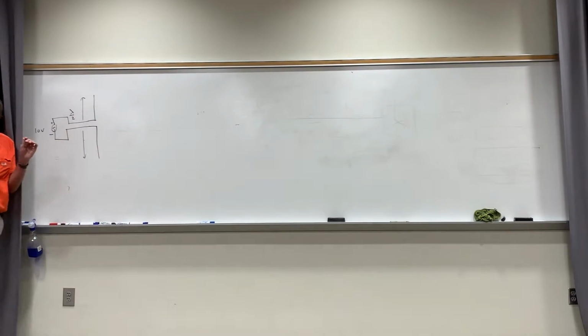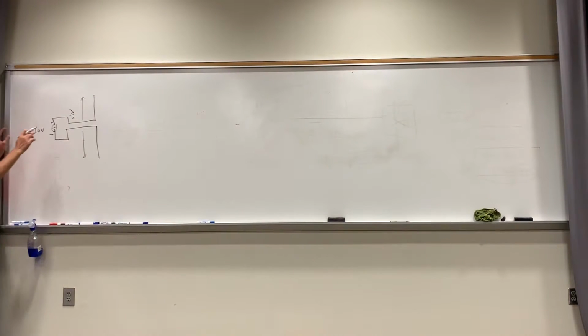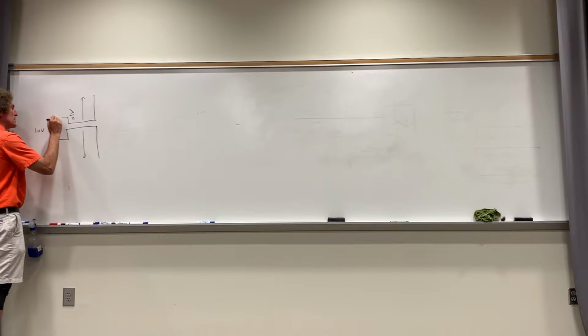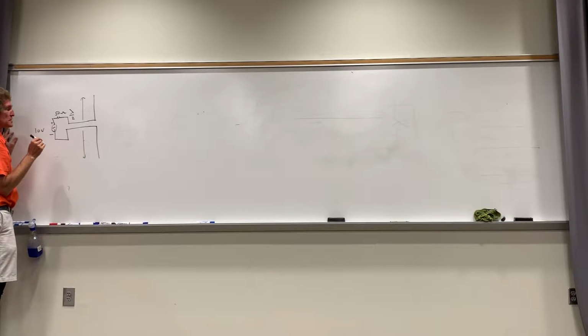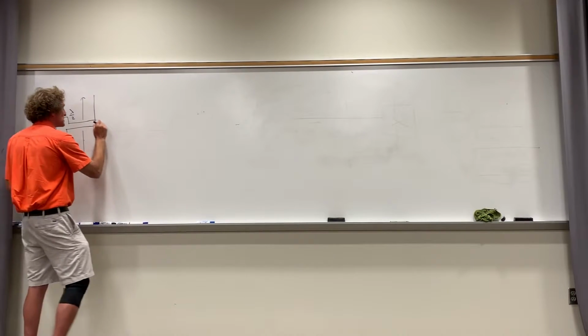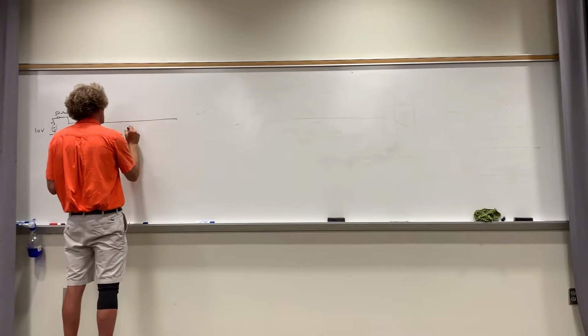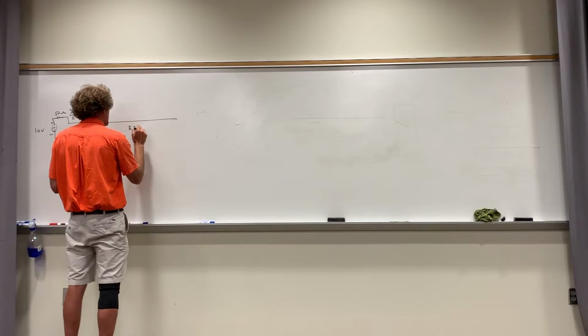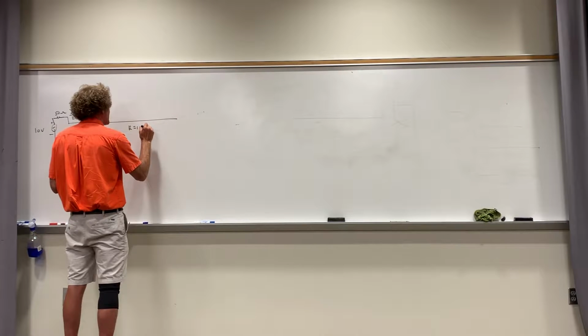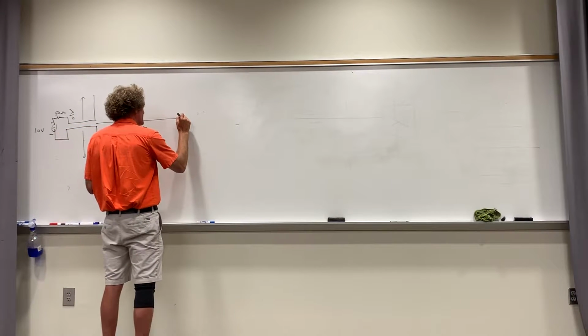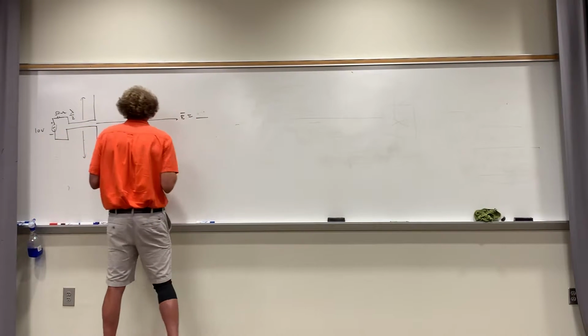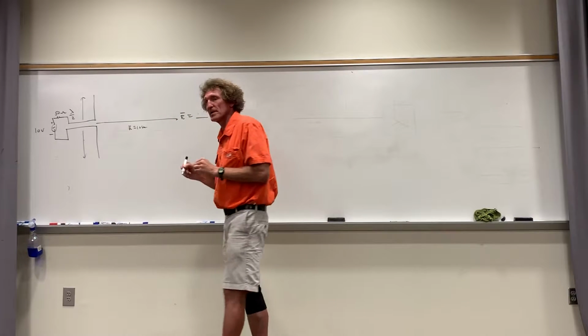So they have an internal impedance of 50 ohms here. Determine the electric field intensity at a distance of 10 kilometers in a plane perpendicular to the antenna. That's maximum gain, r at 10 kilometers, and they want the electric field out here, right? Yes. All right, anybody want to take a shot at this?